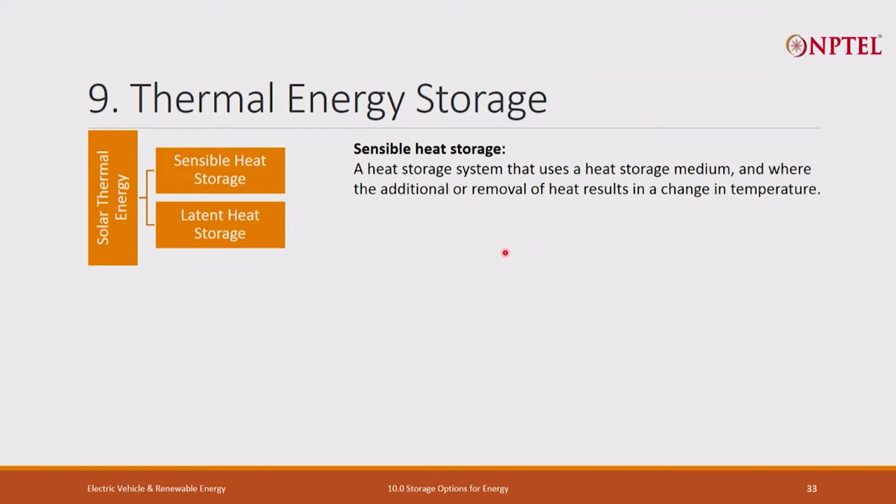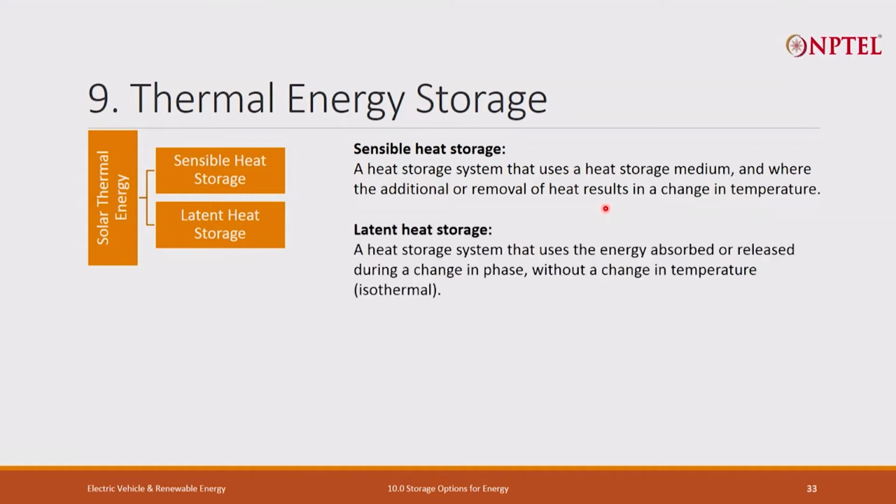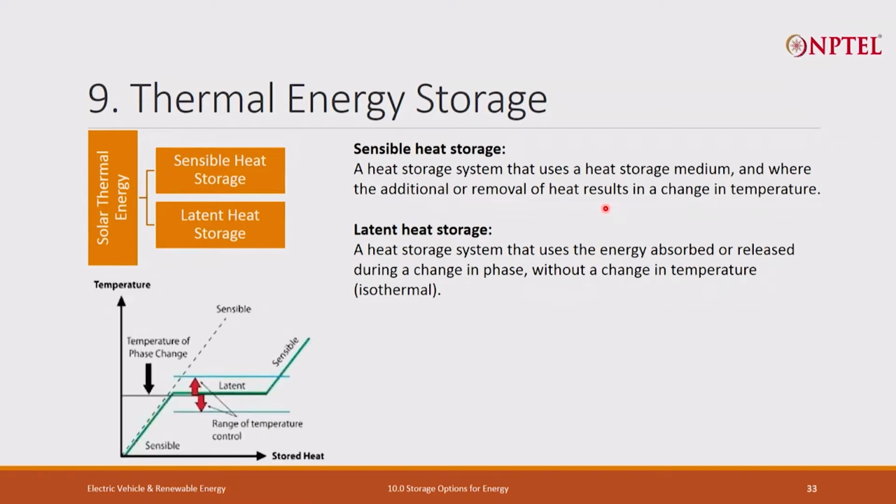In sensible storage, the addition or removal of heat results in a change in temperature. Whenever I take out some heat, the temperature will drop. Whenever I add heat, the temperature will increase. In latent heat, whenever I take out heat, the phase changes, maybe from liquid to gas or gas to liquid. Whenever I add heat, again the phase will change from liquid to gas or solid to liquid. So that becomes latent heat storage.